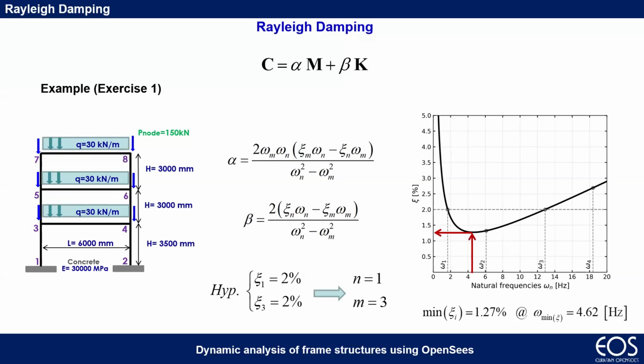Again, it is the stiffness at the moment I'm declaring Rayleigh damping. I'll show you that Rayleigh damping is posing this type of problem in a formal way. But again, if my structure decreases in stiffness, I can go to this point here where I have a lower damping. So pay attention to this stuff here.